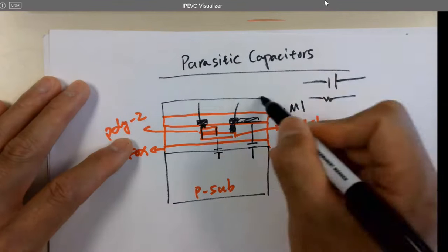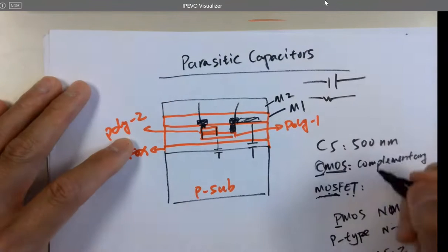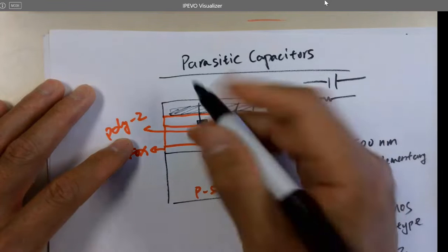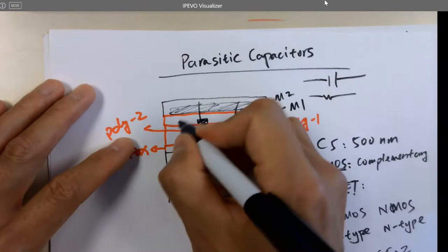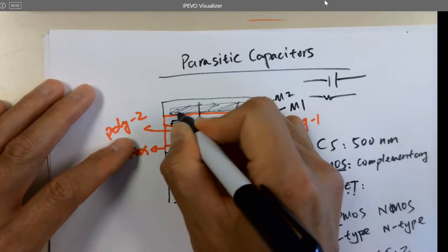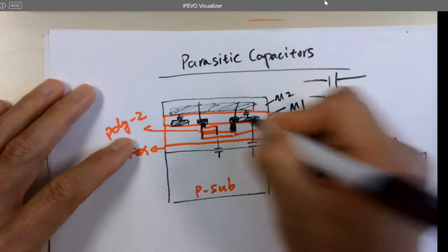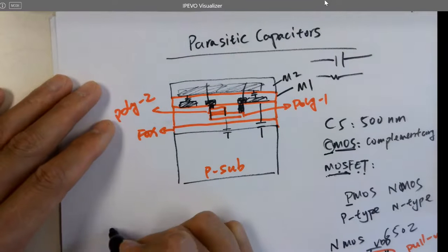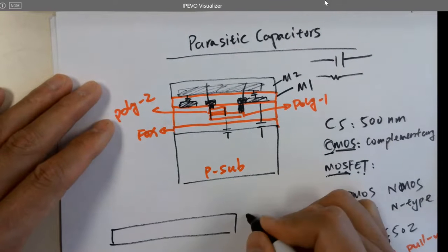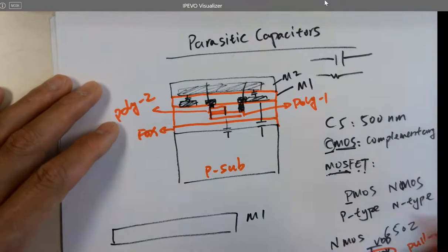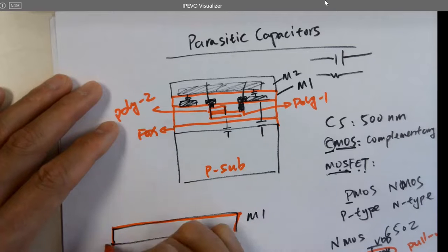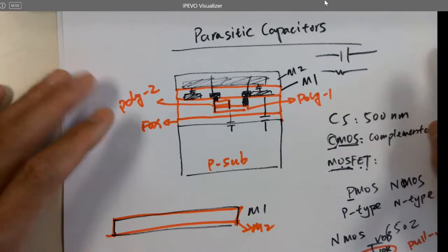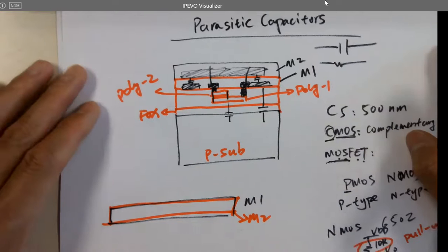And what's the layer here on the top? That's metal 2, right? And if you got a metal 2, it forms parasitics between metal 1 and metal 2 as well. So during the layout, that's why a lot of times when we are laying out traces, if you lay out the metal 1 here, do you think it's a good design to directly lay out another layer of metal 2 on the top like that to overlap them in order to save space? Are we actually saving space on the layout?